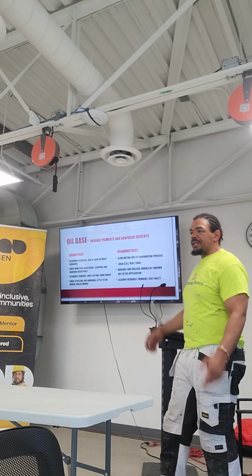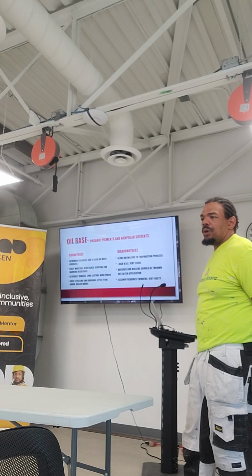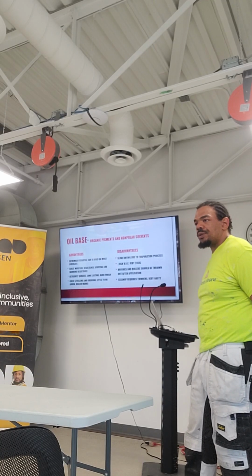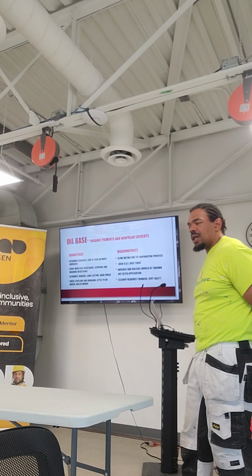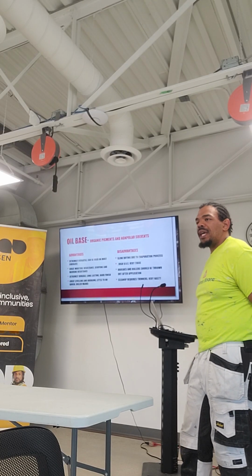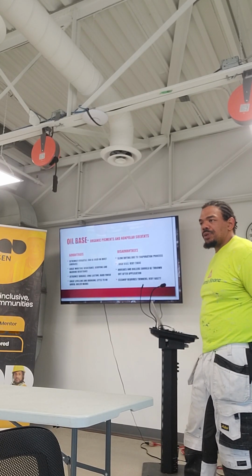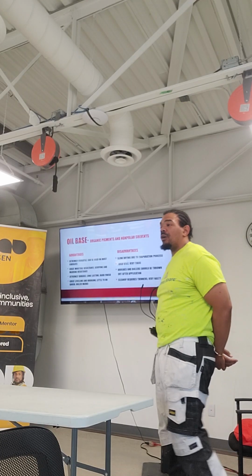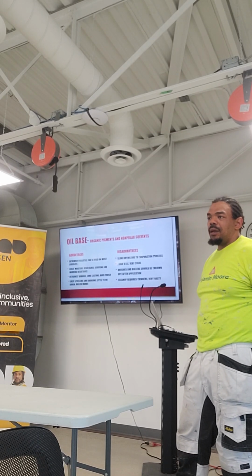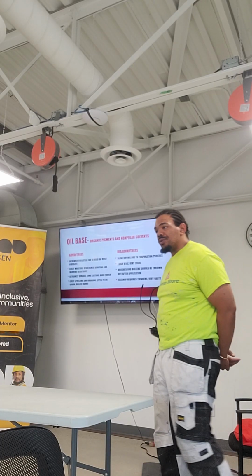And then we get to oil-based. So oil-based paints are traditionally the oldest paints in the world. The first paints were made from animal fats and from oils, natural oils. So oil paints give you the best durability, they give you the most longevity, and they also give you the most headaches from the fumes and the VOCs that you expose yourself to when using them. Oil paints stink for a very long time. It takes anywhere from 8 to 16 hours for oil paints to dry completely. And because of that, a lot of people prefer not to use oil anymore.